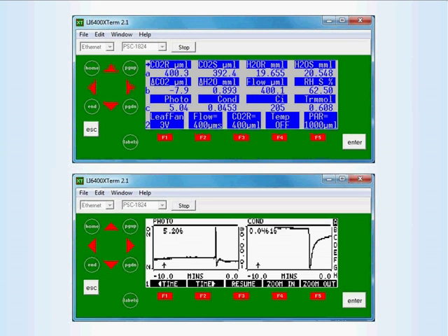Just prior to capturing these display shots, the desiccant control knob was set back to the full bypass position, and the sample and reference gas analyzers were matched again. Notice that the sample and reference chamber water vapor mole fractions are back to the original values of around 20 millimoles per mole, and the sample chamber relative humidity is back up over 62%. The mixing fan voltage was left at 3 volts.